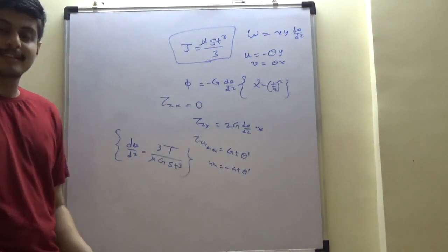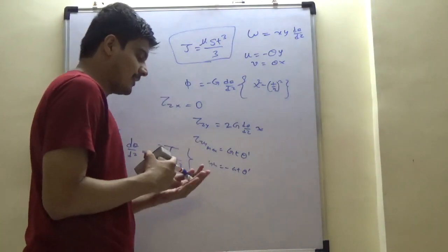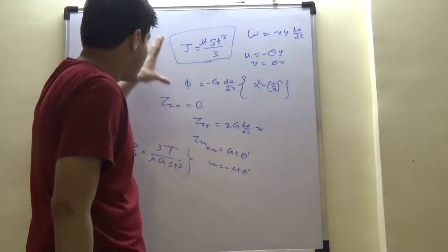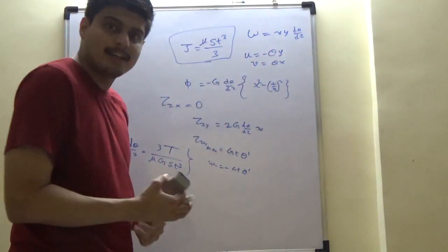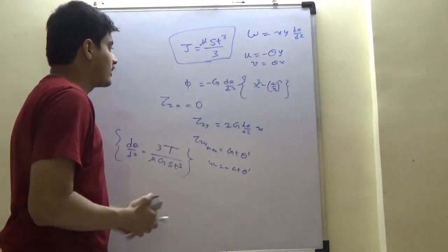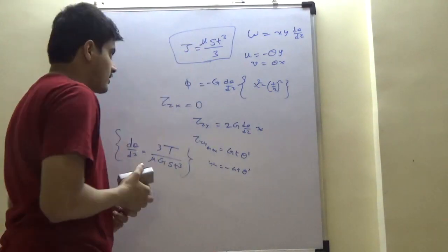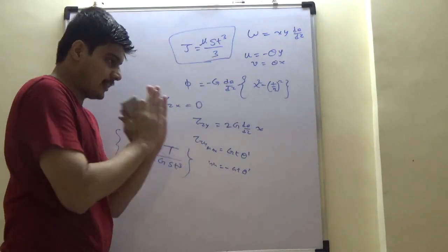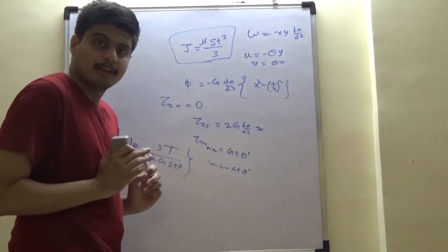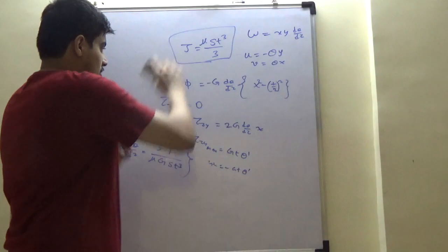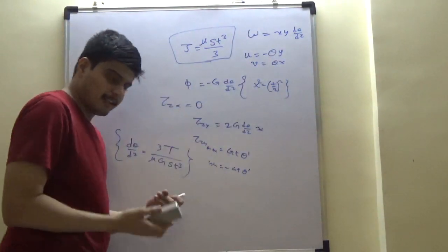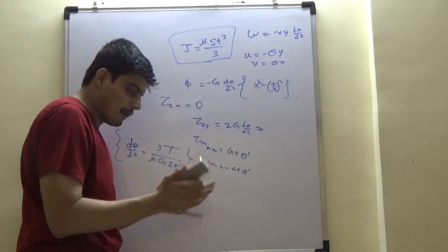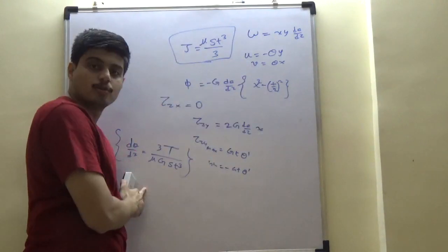And this was the third section of this property of why thin sheets are important. Thin sheets, therefore, we said that for S by T, Prandtl gave us this beautiful analogy and outcomes, and he gave the correction factors. So the entire problem is very easily solvable, and thin sheets are particularly important in our aerospace analysis, because of which this Saint-Venant's warping function and membrane come together to give me this solution.